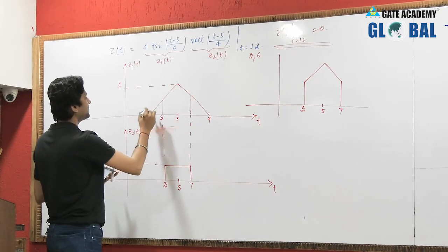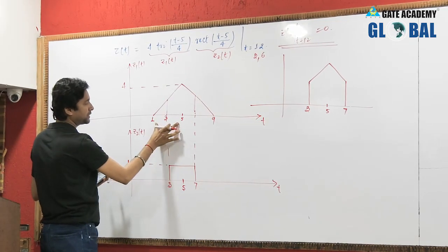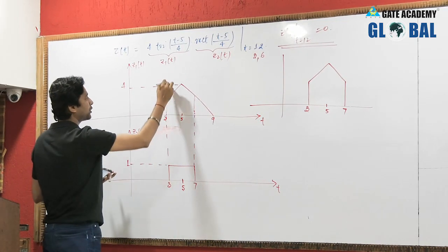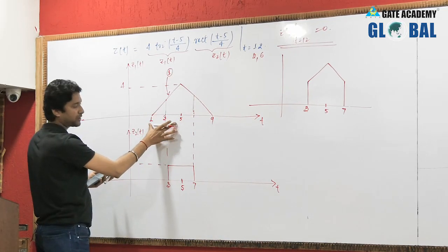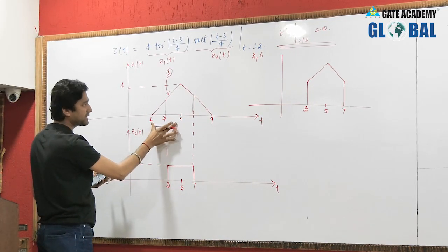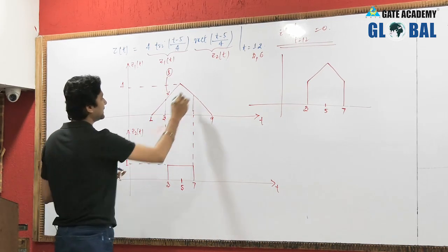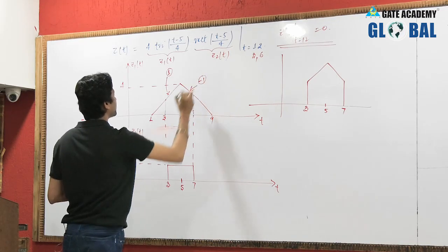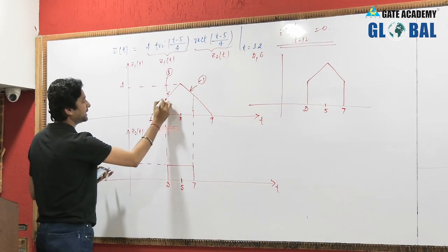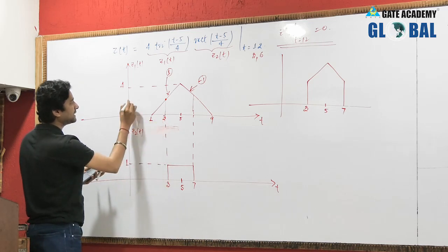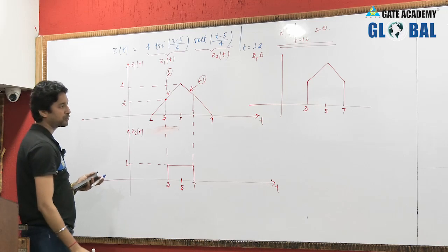And this signal, if it is moving from 0 to 4 in 4 duration, then it means the slope of the signal is 1. As the slope is 1, because if we travel 4 units in time, then 4 value is gained, and for this line the slope is minus 1. So if you have to take the value of this signal at t = 3, you have moved from 1 to 3, that is 2 seconds, therefore the value of this signal will also become 2.